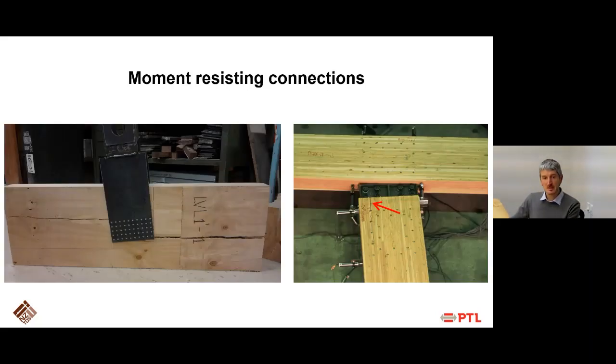Moment-resisting connections. They occur typically when you have barn structures or sheds, or when you have now multi-story timber buildings and you're relying on moment-resisting frames. Because of the nature of moments having different force components which are perpendicular to the radius of the center of the connection, you have potential resultant forces which try to create tensile perpendicular grain stresses in your timber, trying to open up the timber again, which is shown here in these two specimens.